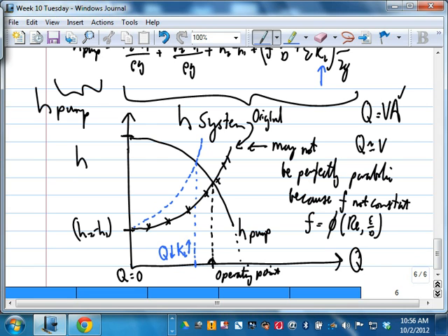Again, this is the first original equilibrium point. This is the second equilibrium point after turning the valve, so expect your flow rate to go down. That's how a valve controls the flow rate. So you still have the pump there driving the system.